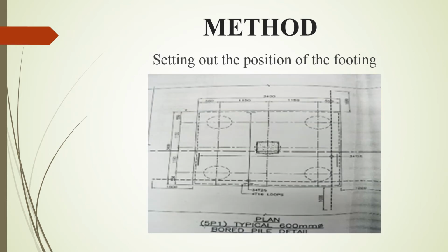Setting out the position of the building. After the piles have been cut by the contractor, the position of the footing should be surveyed by the surveyor based on the position in the construction drawing. The size, dimension, and depth of the footing are indicated in the construction drawing.